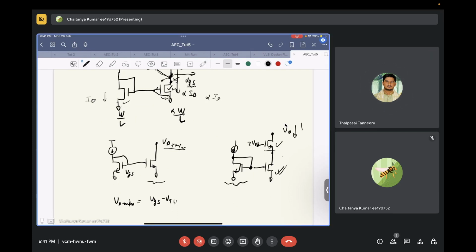Out of this transistor, okay. If there is some change in VD, the drain voltage of this transistor will change by the exact amount of VD, right? Yes, sir. The change in drain voltage of the lower transistor will be higher, lower, or equal compared to the change in drain voltage of the upper transistor. Can you comment on that?